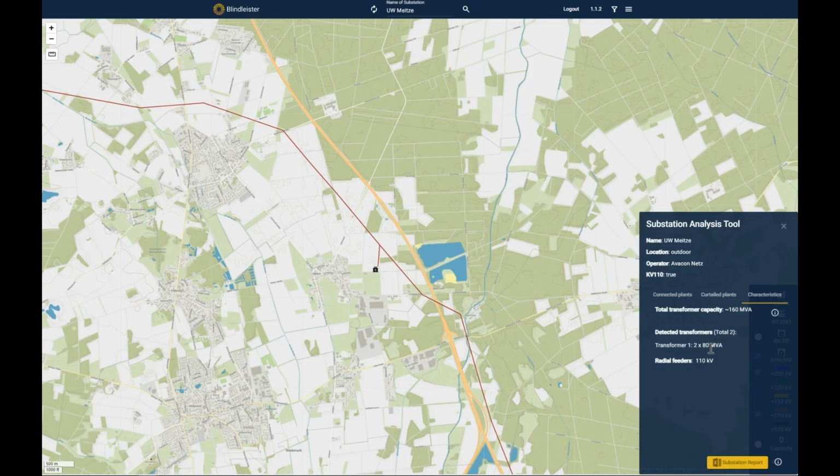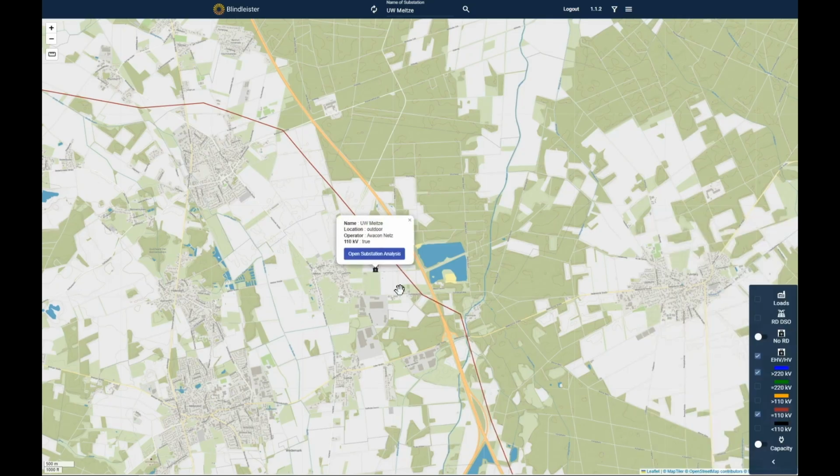So in case something fails, he would say from 160 at least roughly 90 MVA can only be used. So in this case, we assume we have 25 megawatt injecting into the grid maximum, because there is a huge load here, a load center. And we also have only a certain power line here to absorb the additional generation.